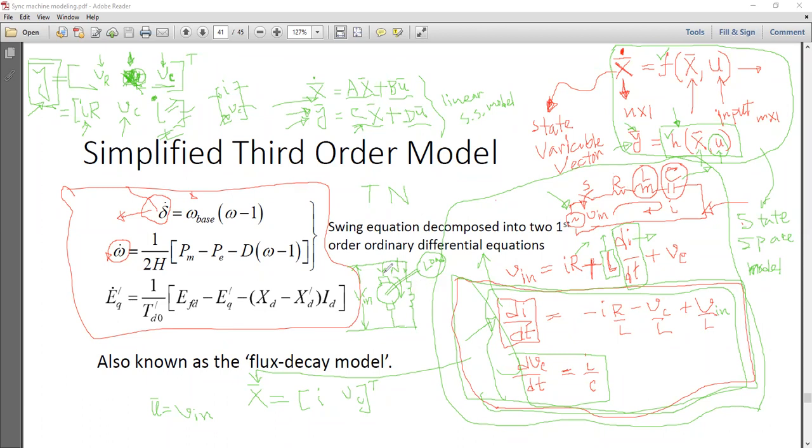Are you getting my point? Yes, sir. So depending on your choice, let's say your target is only to look at the torque. So just keep the torque as your Y variable. No need to calculate N. No need to attach a tachometer with that. Just set a torque meter or dynamometer that would give you the value of the torque. On the other hand, if your target is to control the speed, no need to look at the torque.